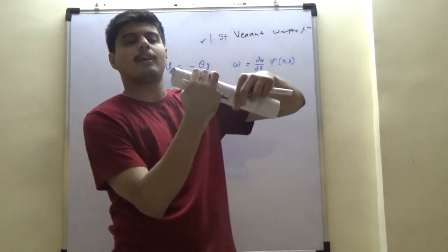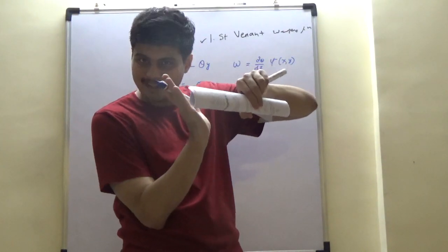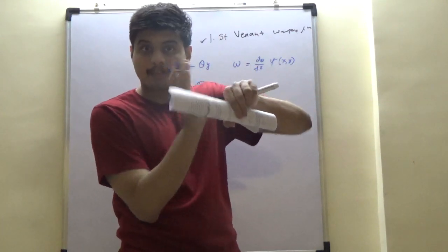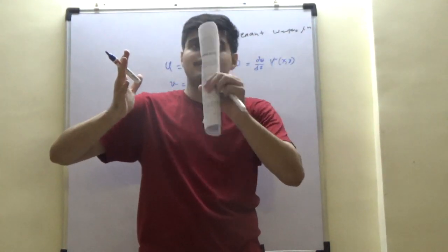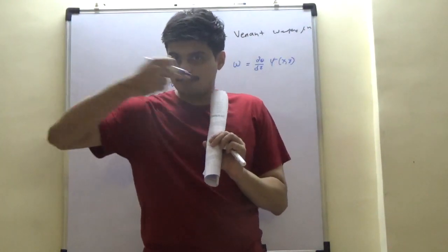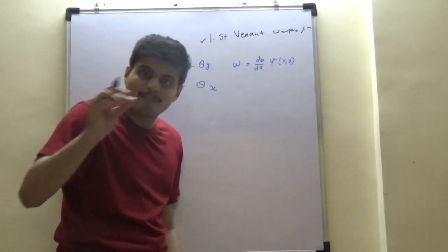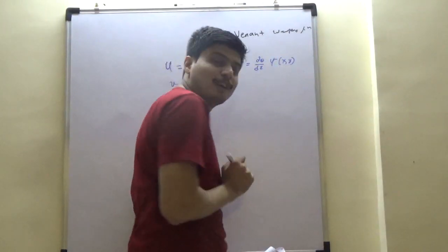If you look at this square, when it warps, the twist gives a projection, right? And the rate of twist is what gives that projection angle. So if this slice is going to move by 30 degree, the slice next to it is by 31 degree, the projection of this line is through that d theta by dz, which is 1 degree, which is protruding out that particular section for a given xy coordinate.